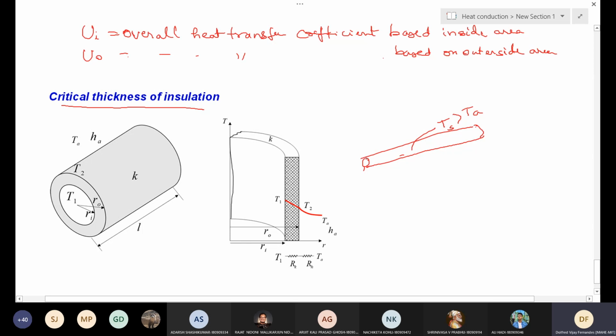So there will be insulation around the wire. One, it provides safety from electrical accidents. The other thing is it also helps in increasing the rate of heat transfer. You are providing the insulation, and my language is maybe completely strange, right? I'm talking about an insulation which increases the heat transfer rather than decreasing it. How is this possible? For that we have to do this analysis.